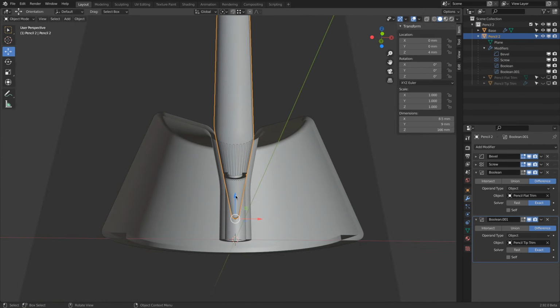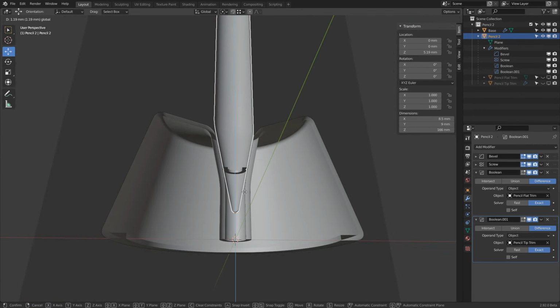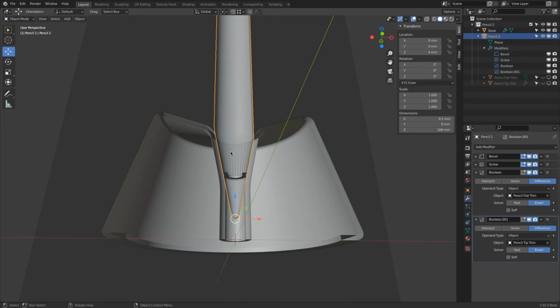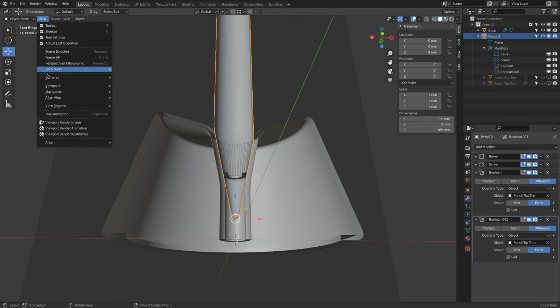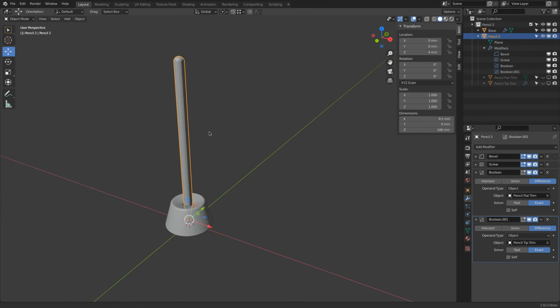It's really nice to see when I now move this, how, for example, would the object fit in? Does it intersect? How much space do I have here at the bottom? So this is actually a really nice tool for quickly looking through an object. To get out of this, we press Alt B again, or just select the command. There we are.